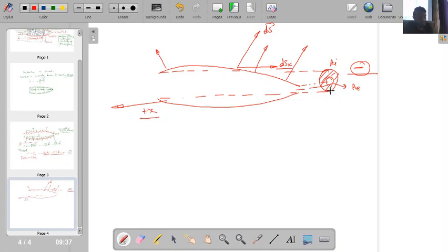Is this one clear? So what you have to do is take the projection. If you take projection of this, you can see some area of this solid object is there in the above portion, but in this area the net projection from this side and this side are actually cancelling out. So the net area which is remaining is this particular portion over here, and that portion is nothing but AI, projection of that in x direction is AI minus AE.